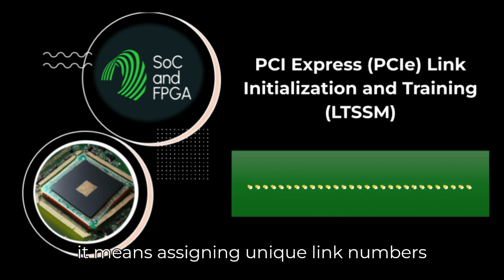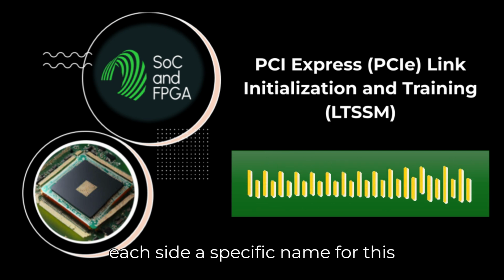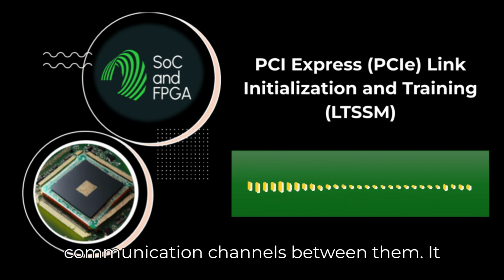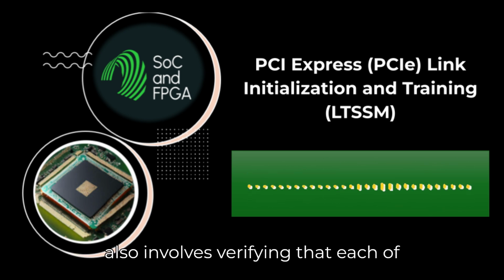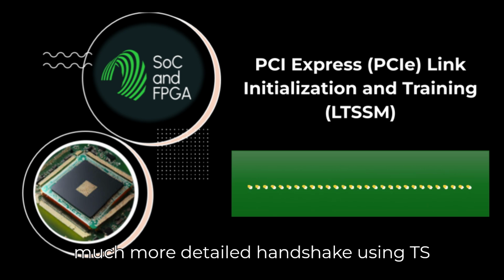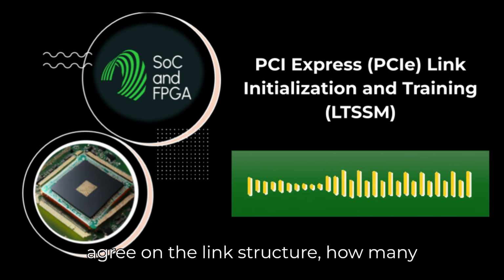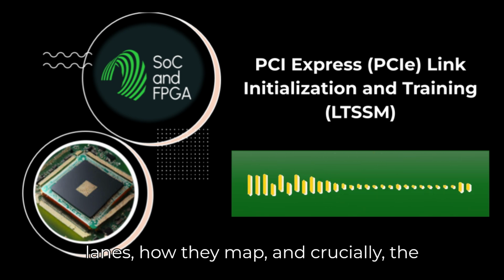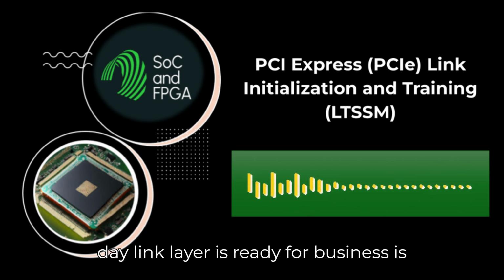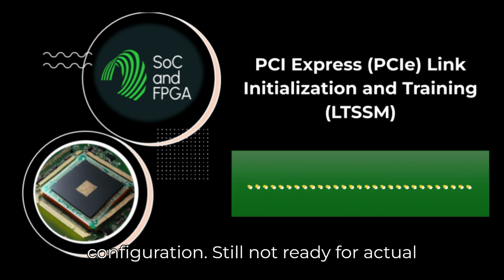Primarily, it means assigning unique link numbers and lane numbers. Think of it as giving each side a specific name for this connection and numbering the communication channels between them. It also involves verifying that each of those lanes is working correctly. It's a much more detailed handshake using TS1s and TS2s to ensure both ends agree on the link structure, how many lanes, how they map, and crucially, the link-up signal, the flag that says the data link layer is ready for business, is still firmly set to off, 0b, throughout configuration. Still not ready for actual data.